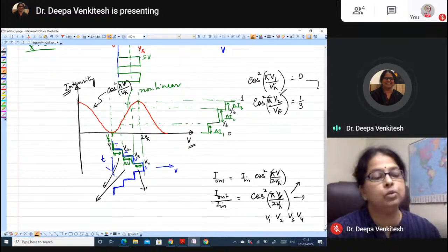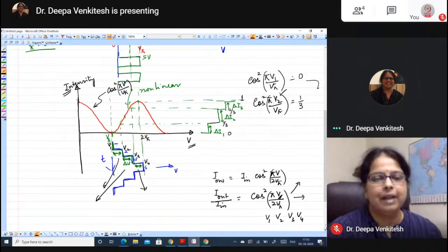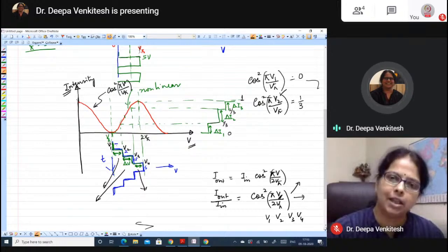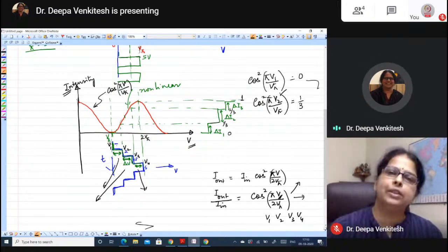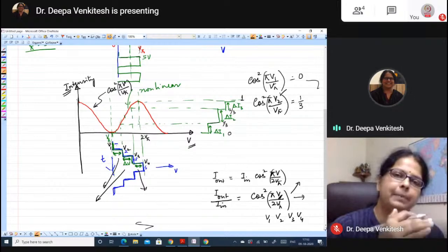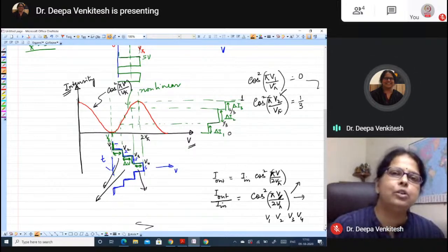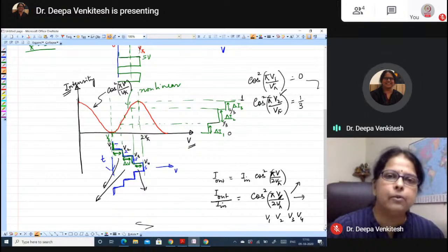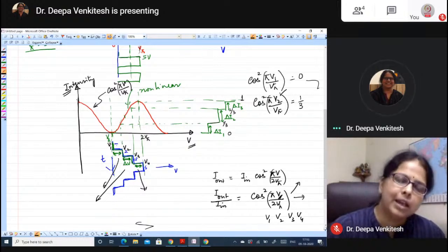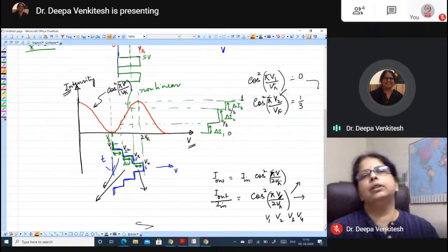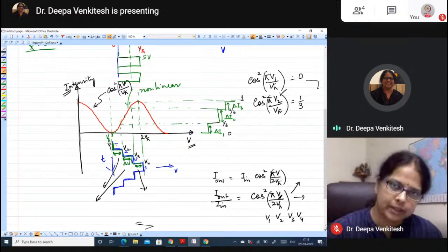You can calculate what is V2, which will give me that answer. So the trick here is to give unequal voltages at the input so that you can compensate for the nonlinear response of the modulator. Now, this is true not just for PAM4, but for any multiple amplitude modulation levels. Later on, you will see in 16 QAM, which is PAM4 and 4 levels of phase, there also you need to do this kind of balancing to compensate for the nonlinear response of the modulator.